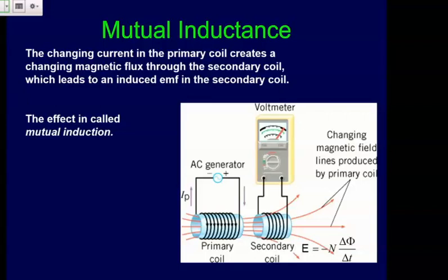All right, so you have this because there's a current here and it's going backwards, and so a solenoid makes a magnetic field, so it's constantly changing its flux back and forth. And this flux goes over here into what we call the secondary coil, and it induces, again, according to Faraday's law, an EMF over here, which you can read as a current or as a voltage. And so that's the idea of a transformer. So you're using this idea of Faraday's law.